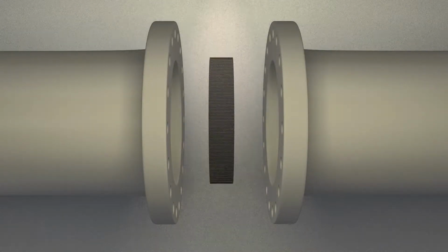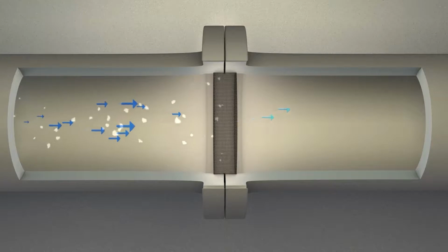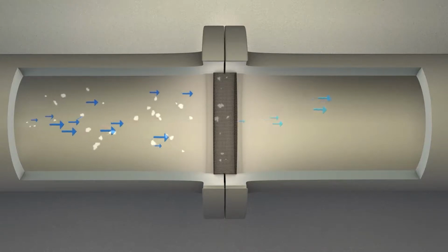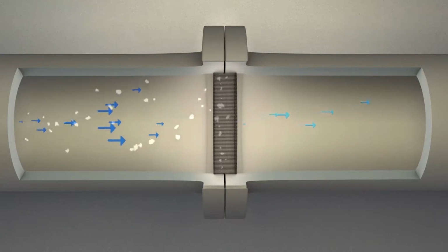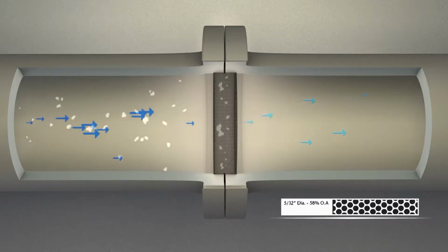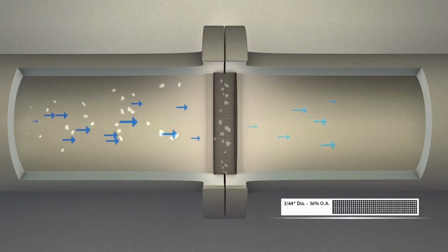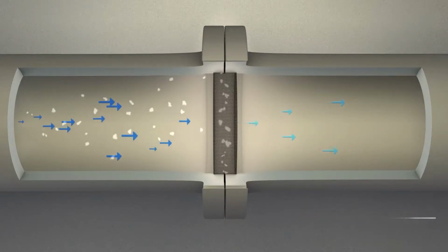Commonly, filters and strainers are positioned to capture solids and particulates. The filter will obstruct the flow through the pipe, lowering the pressure on the downstream side. These effects may vary depending on the filter's construction. Filter media is the material that removes impurities. The smaller the pores, the larger the friction. Higher friction means greater pressure drop.